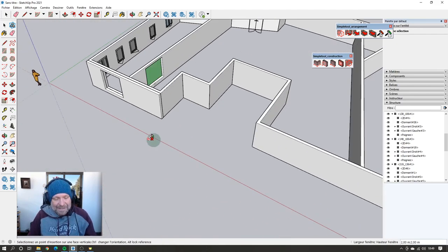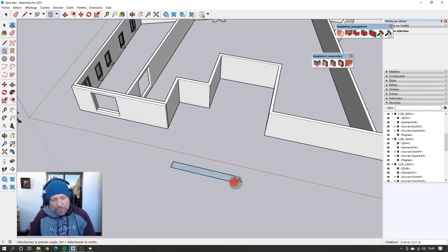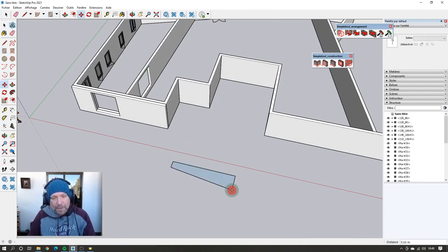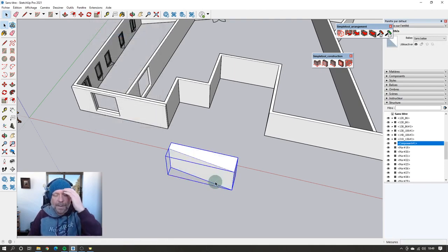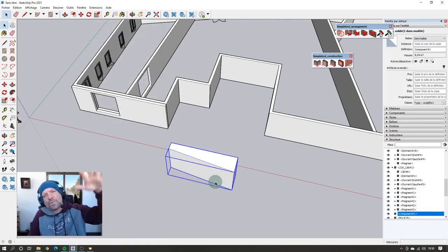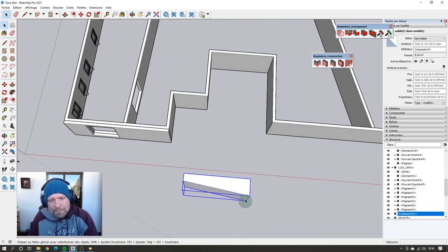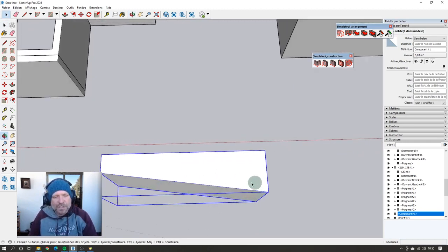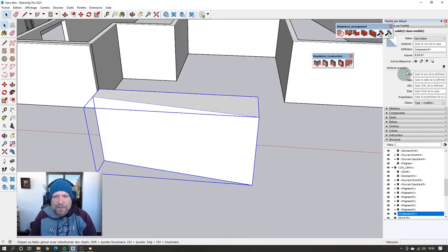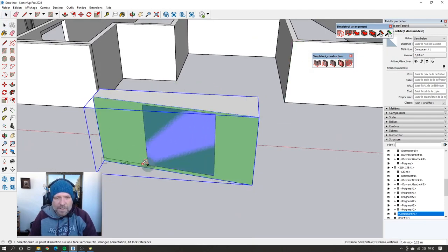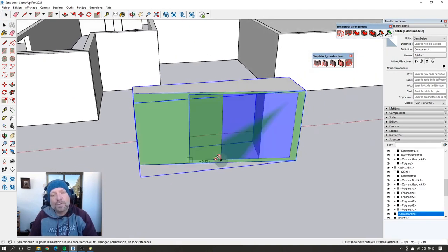So this tool could be used on all vertical shapes. For example, if you import a DWG, sometimes you want to push up all the walls in one time, but on the DWG, walls are not aligned. So here with a simple opening, if you want to push pull the face after that, it will not work.